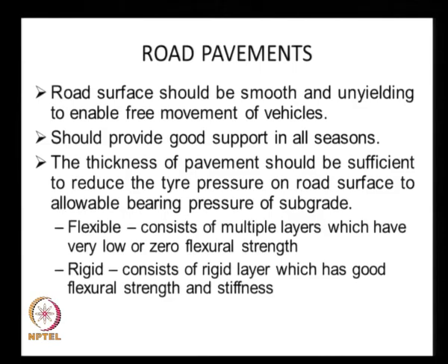That is very important because these roads are open round the year, all the time, and so even in the worst of the rainy season, the road surface should provide a good rideable surface. And the thickness of the pavement should be sufficient to reduce the tire pressures that are applied at the road surface to less than the allowable bearing pressure when these pressures are transferred into the subgrade.